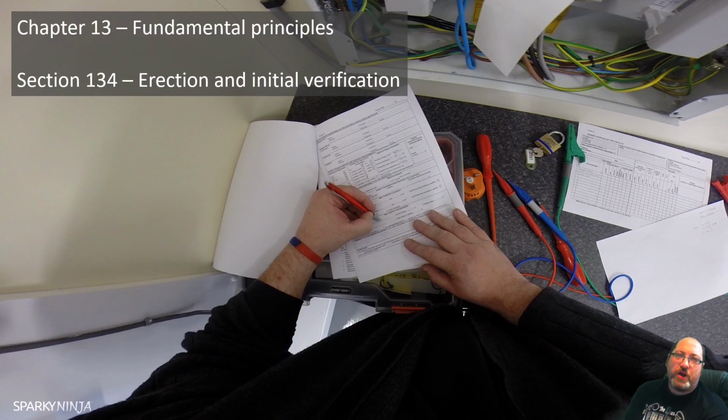Quite often, a lot of electricians or contractors will have a team that do the install and a team that do the commissioning. This can create a problem because you'll end up with limitations or not verifieds on new installations. There should be no limitations, no not verifieds. It should all be ticks or not applicables. And sometimes when we don't allow a suitable inspection during the erection process, there are many things that should have been inspected that cannot be inspected any further. And that's just unacceptable.